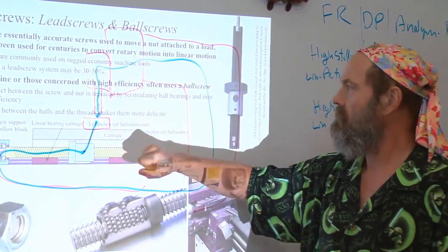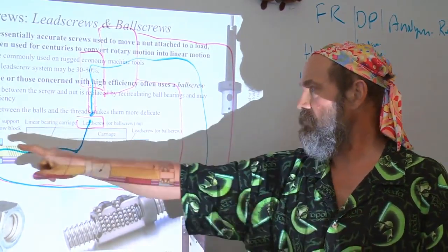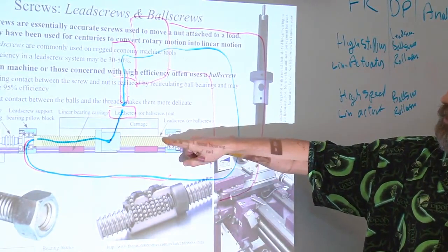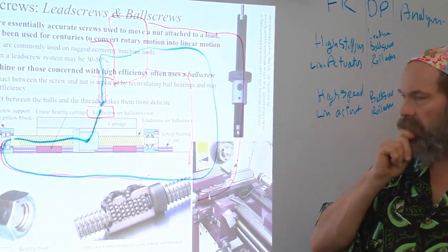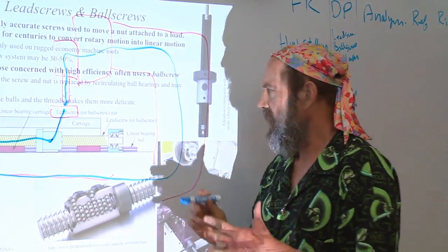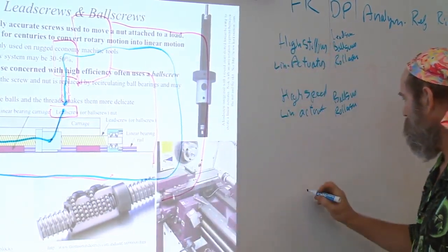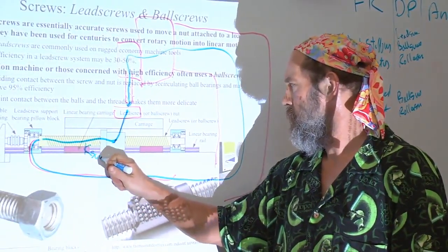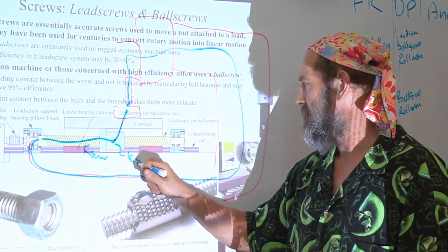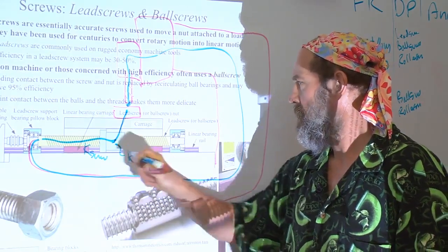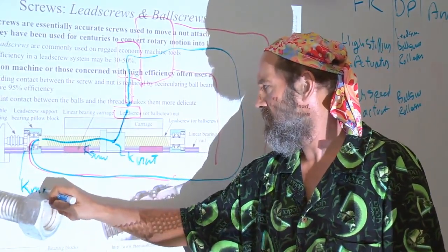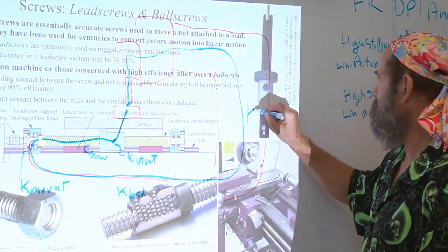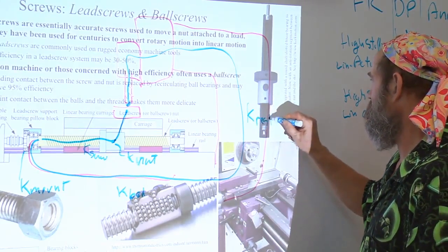So you're worried about screw shaft stiffness. How can I make it better as a structural loop? What is the total stiffness of the machine? Counting your elements in the loop, there's a stiffness of the screw, stiffness of the nut, the stiffness of the mount, the stiffness of the bed, stiffness of the rest of the machine,